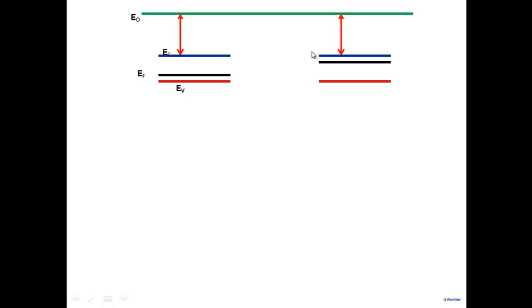And therefore, there will be a field which will go in this direction here, pointing from right to left. And because of this field, the energy bands will bend. And specifically, E naught will bend upwards like this here. It has to bend because, remember, the electric field is nothing but the slope of the vacuum level, and similarly the slope of the conduction band also. So the vacuum level will start from here and bend up here, to keep the slope negative.